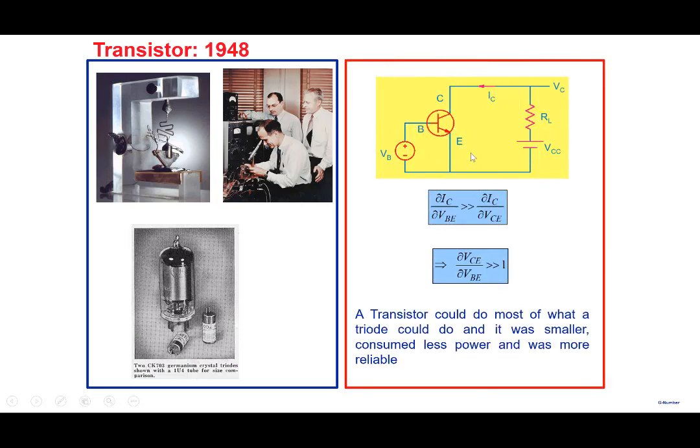The interesting thing about a transistor, you're a little bit familiar with it, is that it also has three terminals. Let's say a bipolar transistor with base, collector, and emitter. Assume the emitter is a common terminal. The collector current flowing between collector and emitter is much more sensitive to the base voltage as compared to the collector voltage. So the same property: collector current depending far more on base voltage, which means transconductance, as compared to collector current depending on the collector voltage itself.